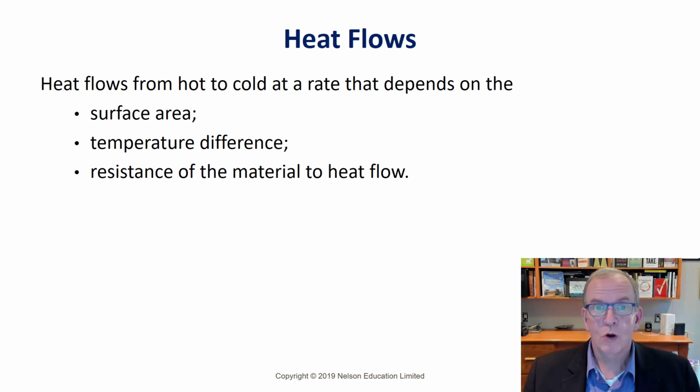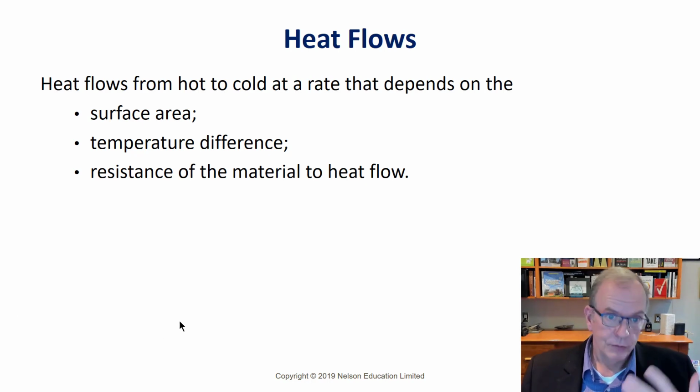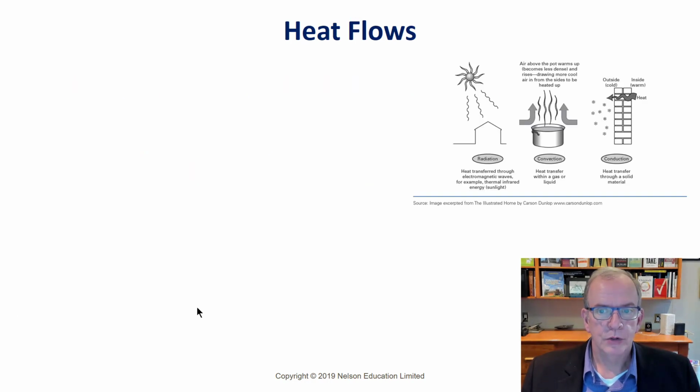How much of it is walls? What's the R value? And that's where you get into the energy modeling aspect too that we talked about in the building systems with HVAC. So you design a system that will ensure that the building is warm in the worst of weather, but at the same time it's running efficiently. And it's designed around how the building structure is.